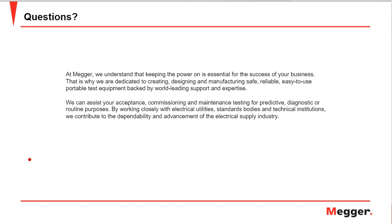If this out of phase condition is not addressed, you could use a phase angle trip supervision, or make sure that the breaker is rated for this application. We have to make sure of those things, or else the breaker may fail to interrupt, and then obviously it will result in a breaker failure condition.